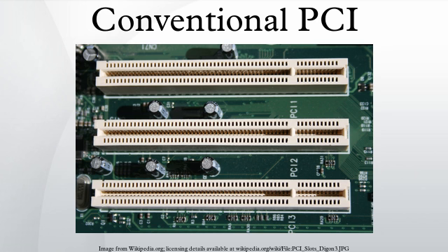Physical card dimensions: the maximum width of a PCI card is 15.24 cm. Two bracket heights have been specified, known as full height and low profile. The bracket or backplate is the part that fastens to the card cage to stabilize the card. It also usually contains external connectors, so it attaches in a window in the computer case so any connectors are accessible from outside. The backplate is typically fixed to the case by either a 6-32 or M3 screw, or with a separate hold-down bracket that is part of the case.